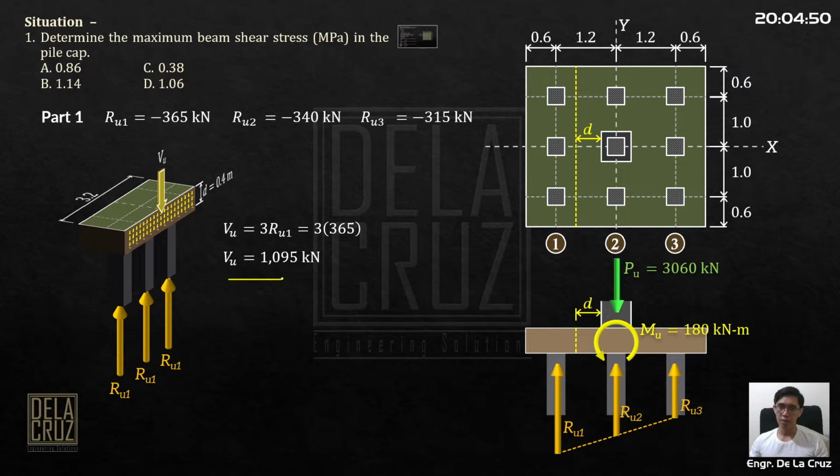And para maging shear yan, divided by area. Force over the area. The wide beam shear stress. I just denoted that one as tau, no? Sometimes, gidenote ko siya sa ibang videos as V, small v. So, basta shear. Force Vu over the area. Ito yung bw times effective depth. Okay? So, we have the shear force, the area, 3.2 meters or 3,200 millimeters. Effective depth is 400 mm.